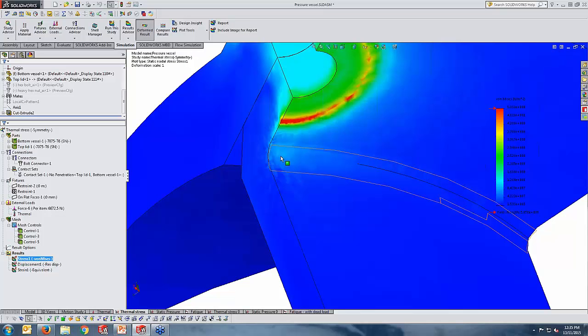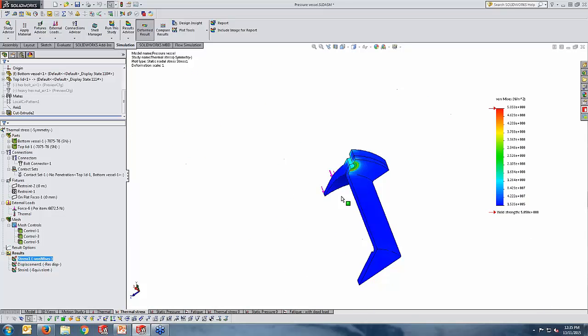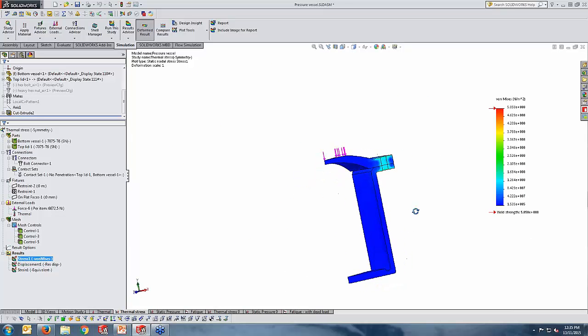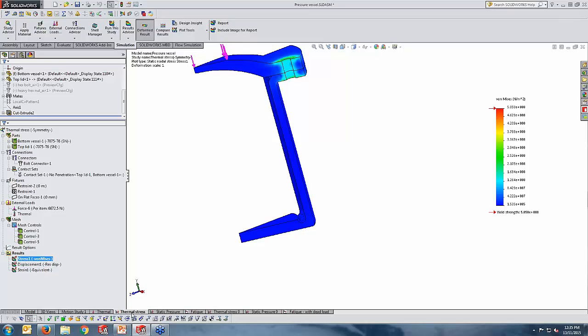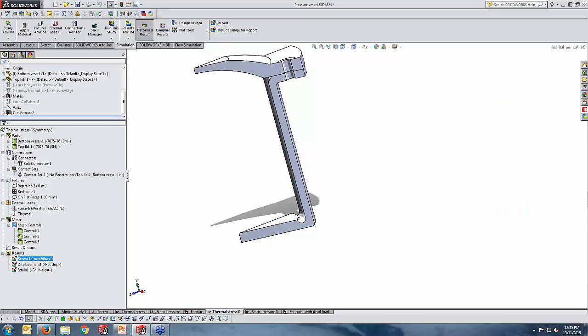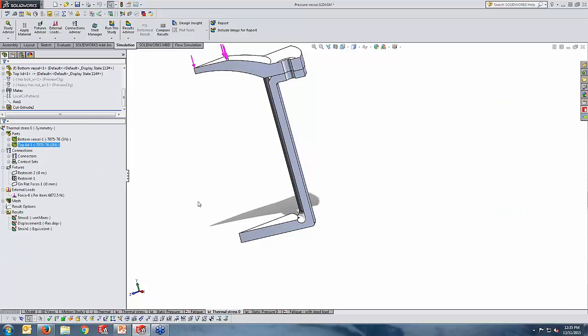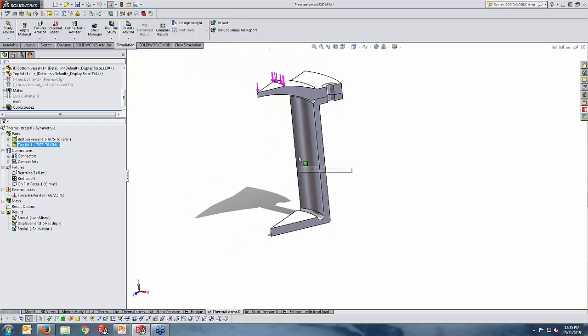load is getting repeated. Now, what we have done up to this point, we have set up two thermal stress studies, one with the maximum heat load, which is connected to that thermal, and the other one without any thermal loads, and it's not connected to anything because there are no thermal loads there. Now it is again the time to make sure we have two more linear static studies, where the pressure fluctuations are considered.